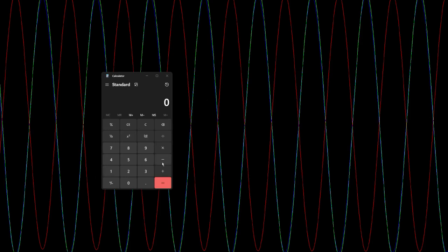So in order to calculate the gain, the formula for that would be Vo over Vin, where the output voltage we got from this graph was 466 millivolts, and if you divide that by about 500 millivolts, that would mean that the gain is about 0.932, which meets our design specification of the gain being over 0.9.